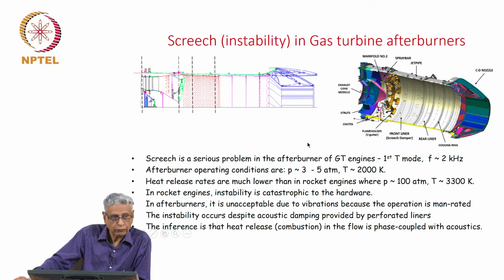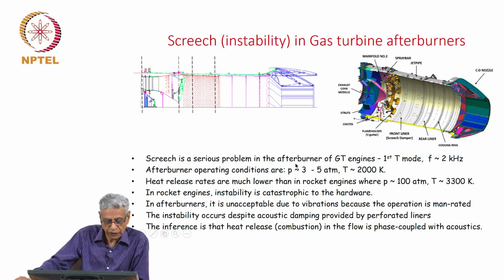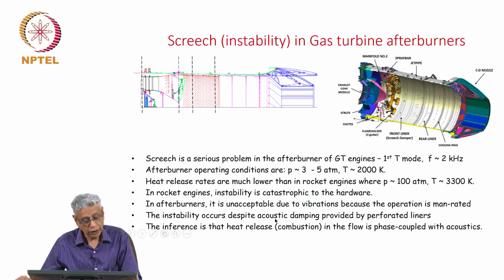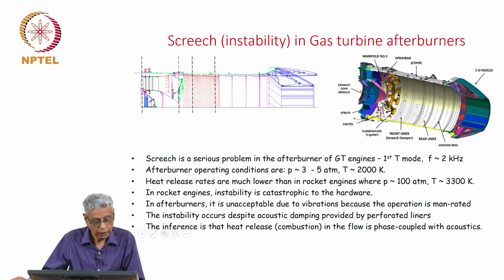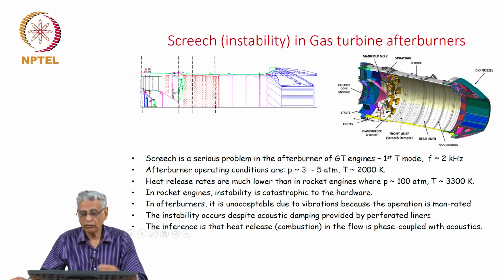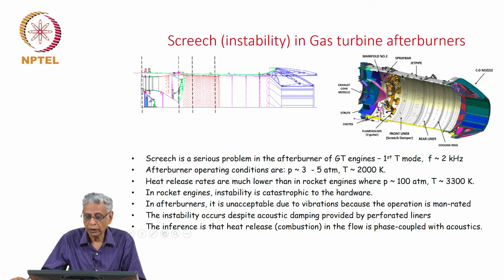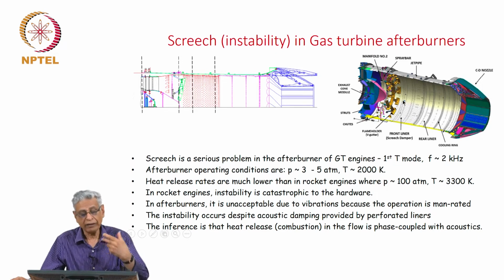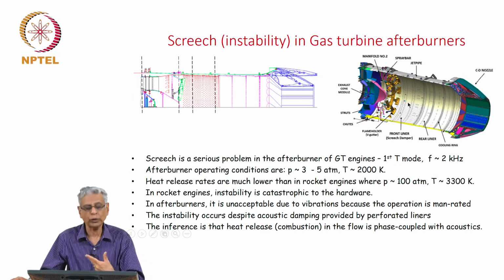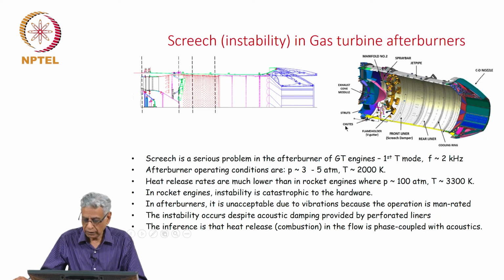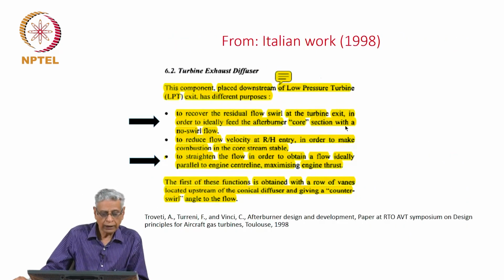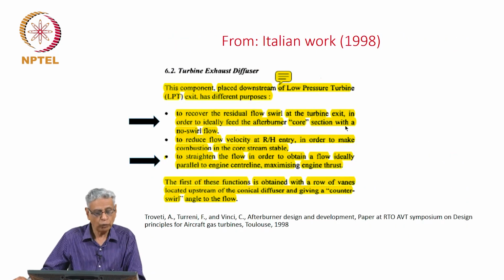In an earlier presentation, I brought out all these features. This instability occurs despite acoustic damping provided by the perforated liners. The Helmholtz effect of the gases coming in from the outer periphery through the holes, taking away the acoustic energy, is also applied here, and they have used advanced design tools to get to that, and yet you find the instability being present.